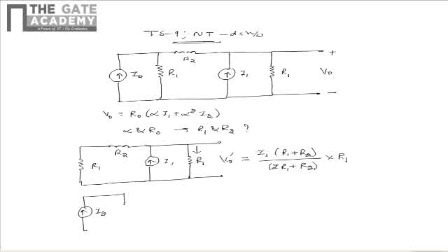When the current source I2 is acting alone, there is a resistor R1 connected in parallel with I2, and there is another resistor R2 and R1 as shown. Please note that in this case the current source I1 is replaced by open because it has infinite internal resistance.